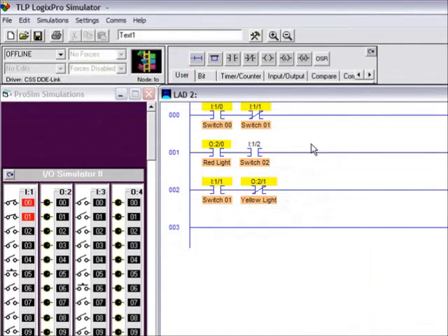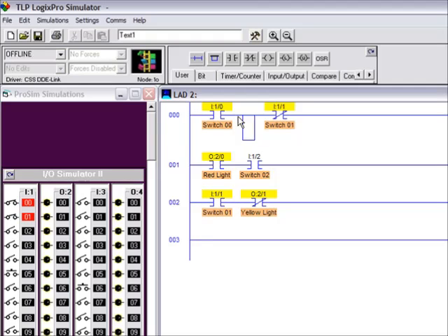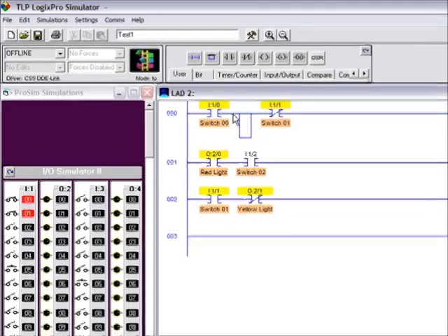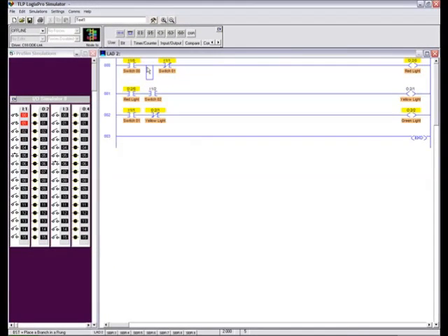So the next step is adding a rung branch to the code. If I go up and click on the icon second from the left in the instruction palette, and I'm going to drag that into one of the green squares here, in this case the one in between the two contacts on rung 0, and release my left mouse button. I've now added a parallel branch to my rung 0, but it doesn't mean much yet because I haven't put a contact in between the two branches.